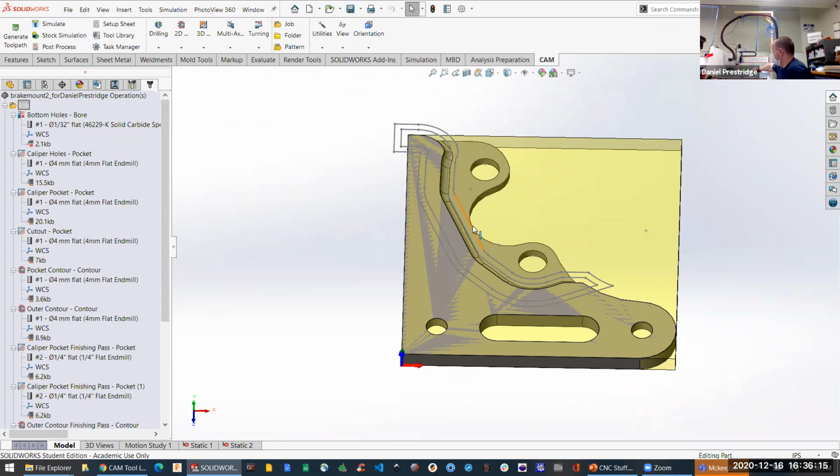So this one's actually bolted directly to the bed, and that's going to give you a lot less vibration. You unfortunately run the risk of maybe running down into the bed if you go too far, because the machine will do what you tell it to do. And if you tell it to just continue going down, it's going to continue going down until it can't go down anymore.